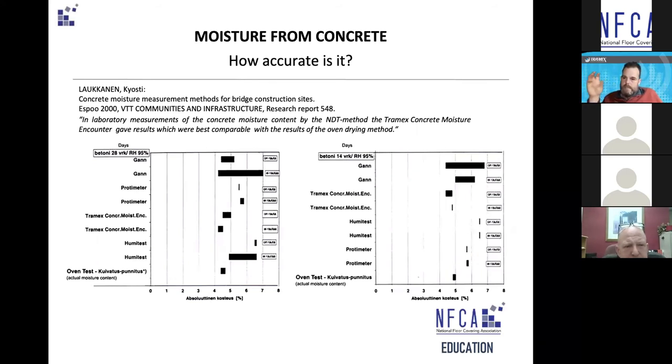So your second point is the ambient. Ideally you want it to be between 70 and 80 degrees Fahrenheit or 20 degrees Celsius, and you want it to be 55% RH. That is the ideal ambient condition. Anything outside that is okay up to a certain point. But if you start to see ambient humidity either very low or very high, then that should be a big red flag for the need for more testing.